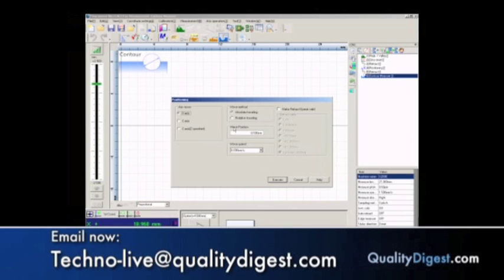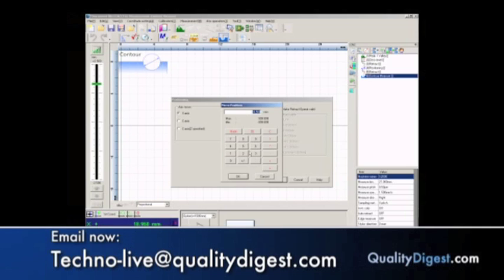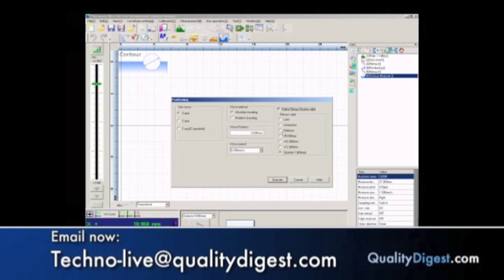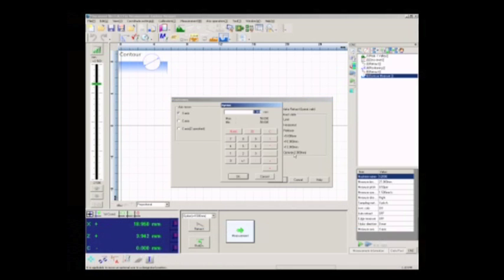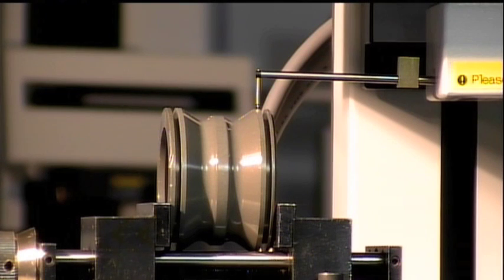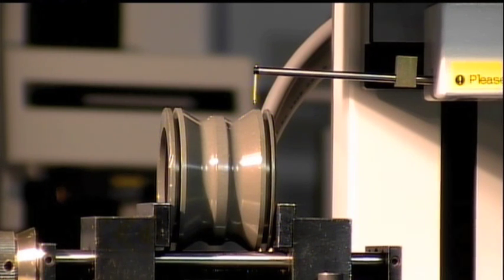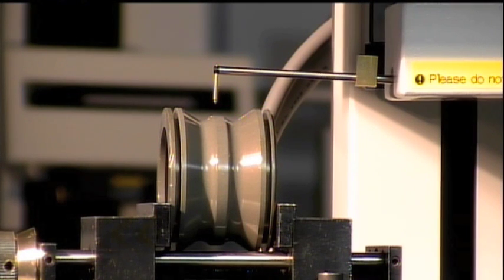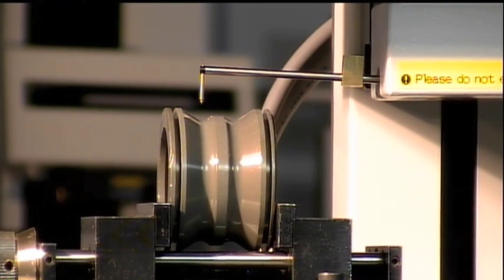And in this case, I am again going to make an x-axis move, and I'll make it back to 0. And this time, I'll actually do my stylus raising right inside this move, just to illustrate that can be done. So this is actually 2 moves at once. It's going to raise the stylus up 1 millimeter, and then do the x-axis move. And so this is retracting, and that gets everything out of the way, ready to unfixture the part. That's right. Go ahead and release that for right now.